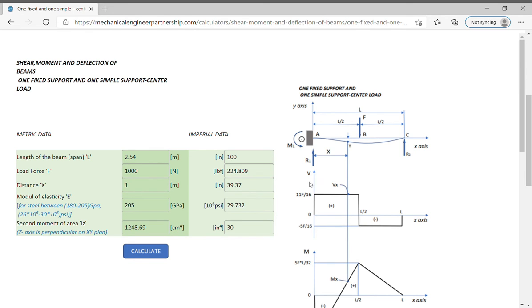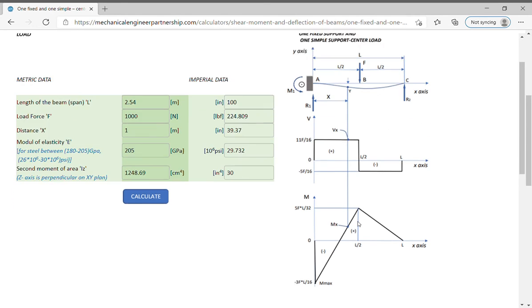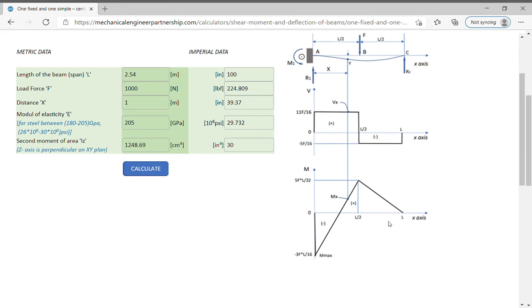Analyzing the graphic we observe the shear force is positive between points A and B, and negative between points B and C. The maximum absolute value of shear force is between points A and B. Bending moment is a linear function of the x coordinate, negative or positive, and maximum in absolute value at point A. B is an inflection point of the bending moment, smaller than the bending moment at point A. The moment has zero values at point C, and at an x-coordinate value between A and B.